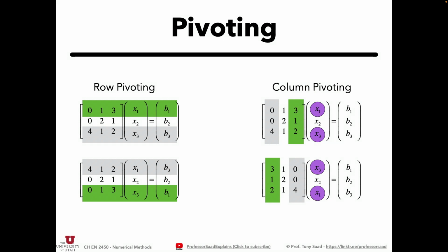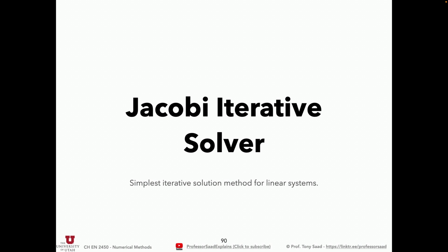All right. Now we get to the first solver. The Jacobi iterative solver is the simplest iterative solution. It belongs to a class of academic type iterative solvers. We rarely use those in real practice. In real practice, we get to these high order Krylov multigrid spaces, which are beyond imaginably complex. There are people who dedicate their lives to studying these, to developing these solvers. But yet, it doesn't mean we cannot understand how they operate in their essence.